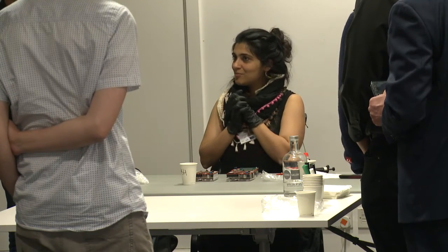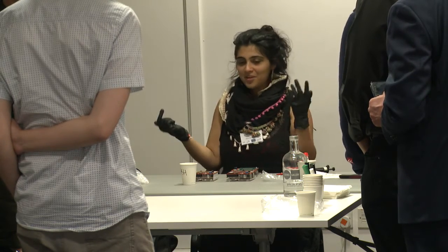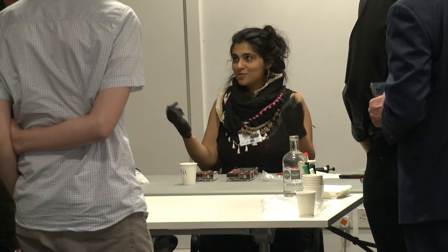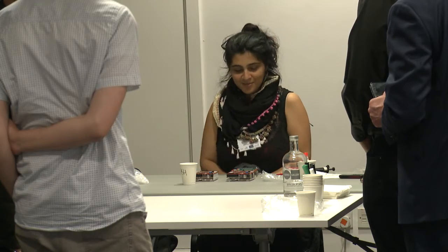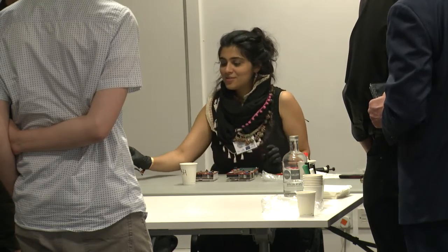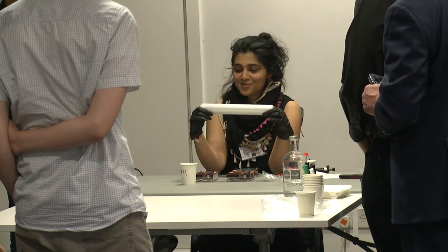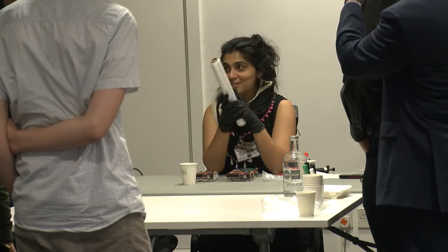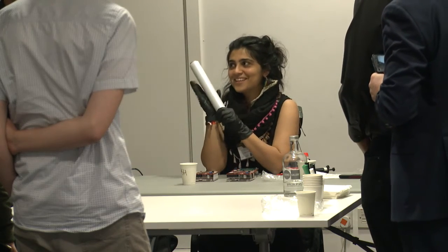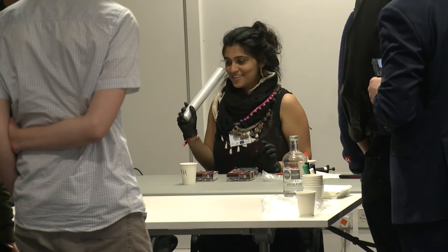The second thing is that some of them deliver samples in huge rolls, and they were holey. They had holes in them. Because for an airplane, probably a 1 femtometer hole doesn't matter, but for me, it's enough for my electrode to jump around and make a mess on my biochip. So eventually, we ended up using kitchen foil. I can name it in many languages, most of the languages where I gave my workshops on it. It has a very nice dielectric constant, a thickness of 10 microns, so it's just enough to use on a microfluidic biochip. I'm not saying this is the final solution, this is the current solution.